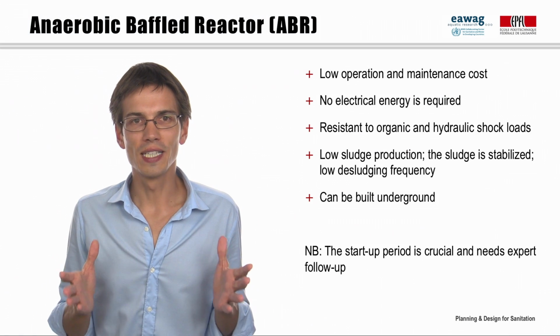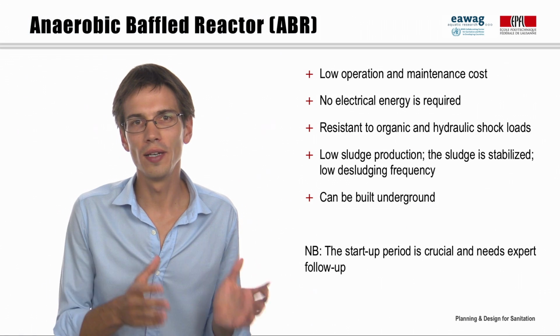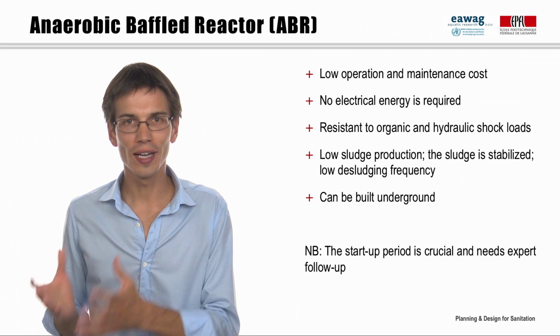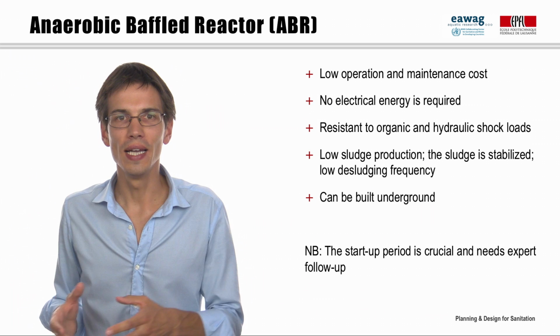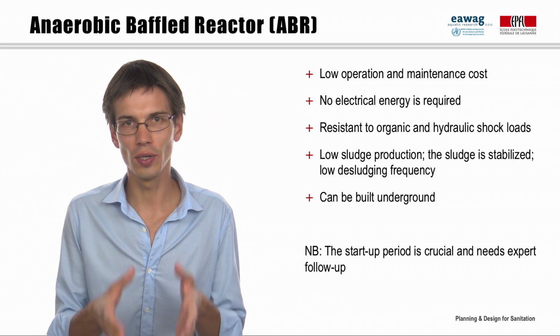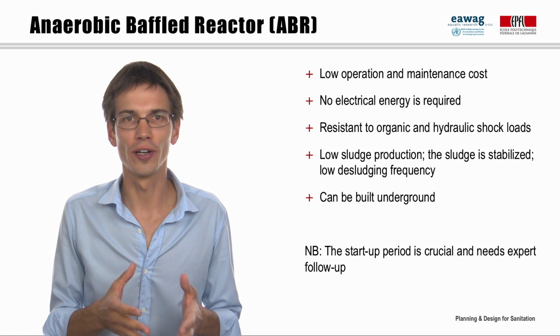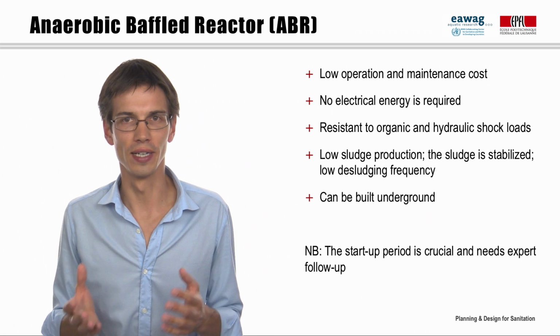The ABR presents many positive aspects for low and middle income areas. It has low operation and maintenance costs, no electrical energy is required, and it is resistant to organic and hydraulic shock loads. As for the sludge, the retention time is long, from 6 months to several years.